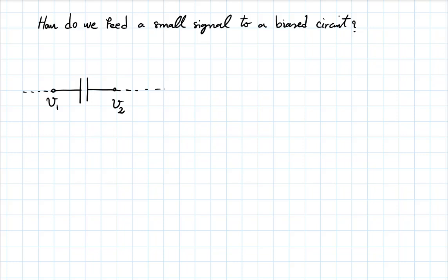The capacitor would do that. So for a time-invariant, DC signal, the capacitor is an open circuit. But for an extremely rapidly changing signal, the capacitor is a short circuit, because if you change this side, the other side will also follow momentarily.